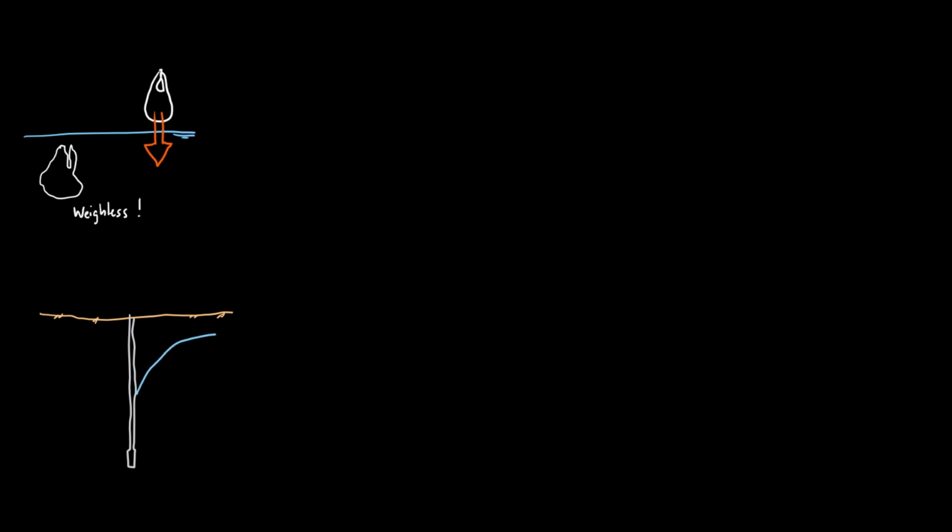Headwise, we start with a heads up. Imagine for a second a bag drifting inside water. As long as it is within the water, it is weightless. It's only when you start pulling it out of the water that you feel the weight. Similarly, the pump may be very deep in the water, but it will only feel the weight when it starts pumping out of the water. So we only care about where the water surface is and not the pump.